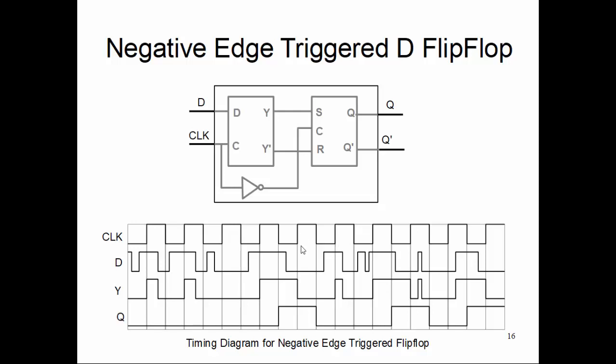So that becomes low. So this is what the flip-flop does. It basically registers an incoming value on the D at one of the clock edges and reflects that value at the next clock edge, the negative clock edge. Let's say it is a positive edge, it is registering that value, and at the negative edge, it is reflecting back.